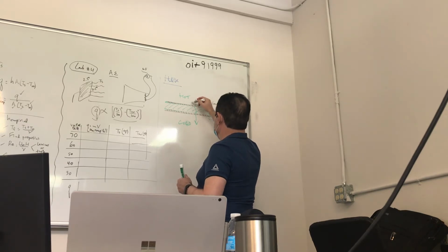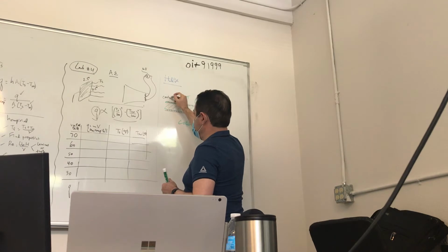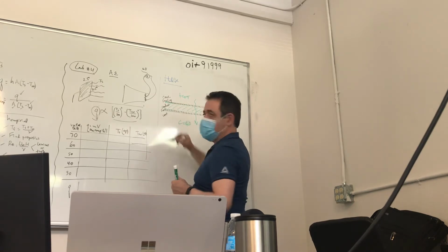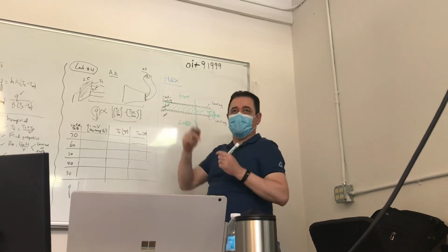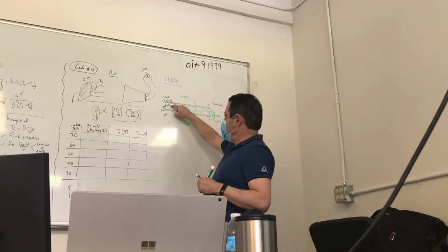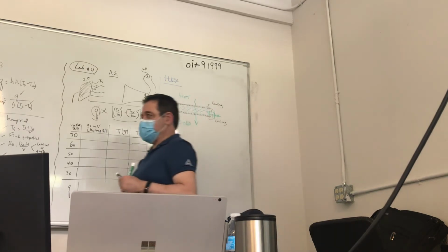And then you usually have convection resistance, right? Then you're going to have fouling. Then you have conduction resistance, right? Then you're going to have fouling. And then you're going to have another convection resistance, right? 5 things to go through, right? So convection, fouling, conduction, fouling, and convection. So total number of 5 resistances.